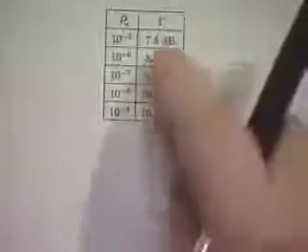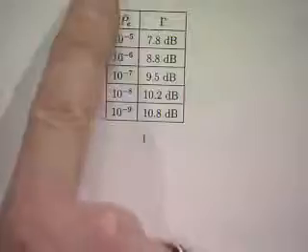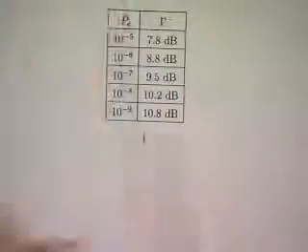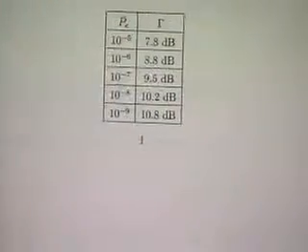Now there are modulation techniques that are better than PAM and QAM. There are more than one or two dimensions used in those transmission techniques. They're multi-dimensional transmission techniques called codes, which have smaller gaps. Codes exist that get pretty close to 0 dB on the gap, but they're very complicated to implement.